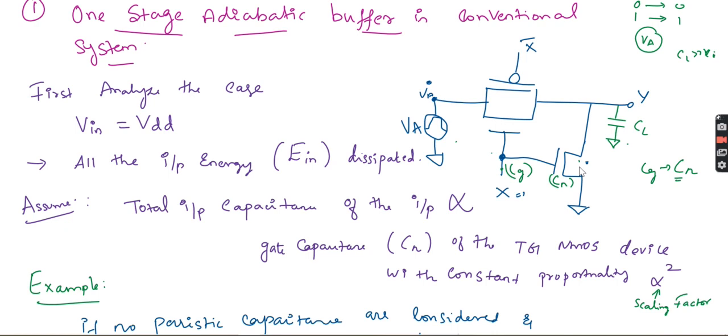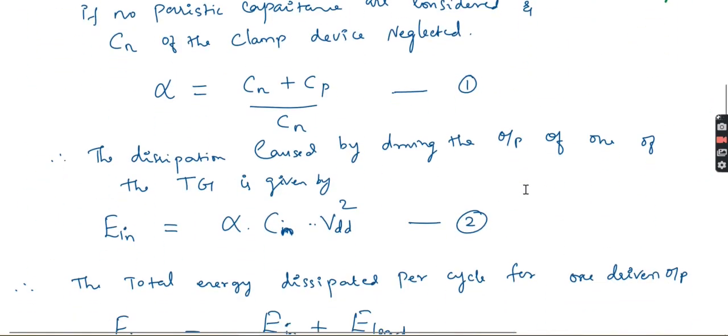As you know, when you take any NMOS transistor, you might have studied that many capacitances will be there. That is the junction capacitance, and all around the terminals there will be a capacitor. For example, the capacitance between gate and drain, between gate and source, between source and bulk, and between bulk and drain. That we can call the capacitance between drain and source. Then the capacitance between gate and substrate. So there are various parasitic capacitances available there. Here we are considering no parasitic effects, only capacitance.